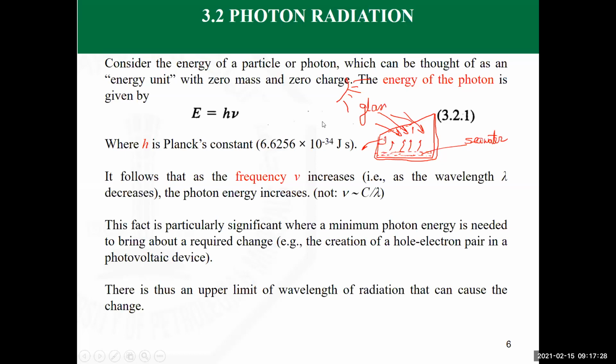And then lots of improvements have been done, like for example, using wax somewhere below this absorber surface so that the wax melts during the day by receiving energy from the sun, and then after sunset the wax is going to start to solidify. As it solidifies, it's transferring its latent heat of solidification to the water, so it keeps the water hot for about maybe 2 to 3 hours after sunset, and still the unit produces. So there are some ideas, all of them are related to the issue of receiving the energy and storing the energy and making use of the greenhouse effect in this case.